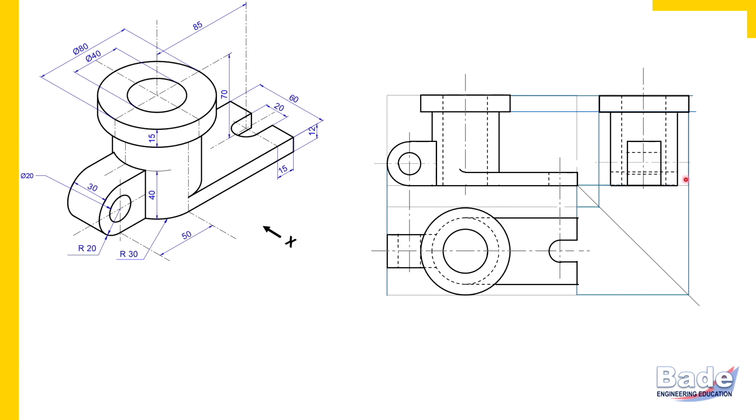Where is this base plate in the side view? If I ask you, you should show me the complete rectangle. Check here, it is attached to the cylinder from the right side, and the side view is the left side view. So from the left side, this plate is hidden. So there is a dotted rectangle here. Watch here, this is that rectangle. But its three edges coincide with the earlier drawn continuous edges. Okay, you never draw hidden lines at the boundary, remember.